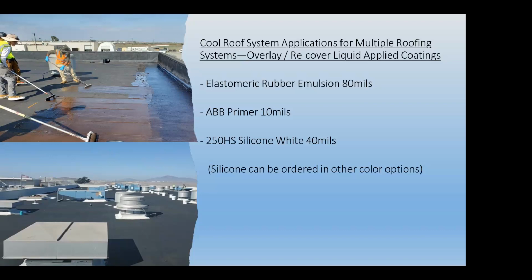The overlay systems with that new membrane, you have a 20-year warranty. The possibility is if you're putting silicone on there, you can actually extend it out 25 and 30 years with the IPP overlay system. So you keep track of all your records, you have the warranty in place, NDL, whatever warranty you went with, and you're going to extend this out up to 30 years.